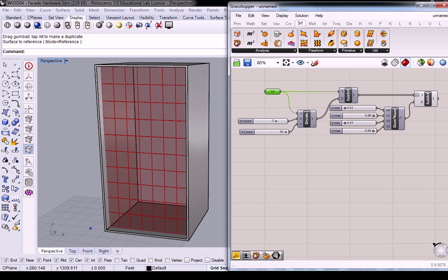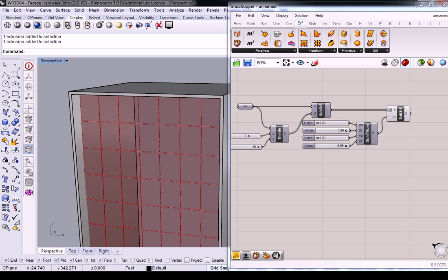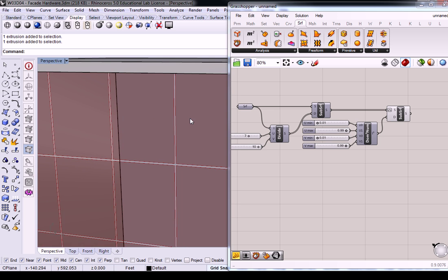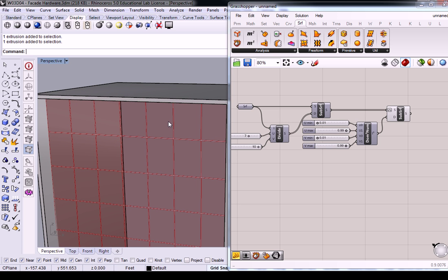Okay, so I'm going to pause and make sure you're all caught up before I continue. Now where I want to get you to at this point is to set up the surface box in a position to locate your hardware. And then we'll do the locating the hardware part later. Basically, the first part of this is you take these surfaces and you can set up your surface box directly on them, right?